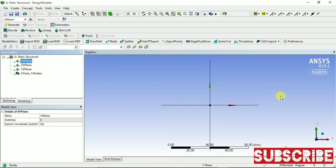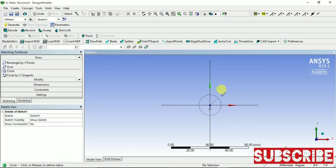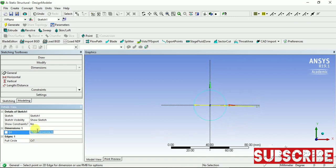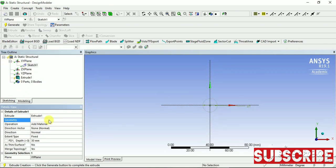I will show a very basic example to use this software. For example, say we take a cylindrical specimen. For that I will use a circle with a particular diameter, d1, say 15 mm. Okay, now go to modeling and extrude it. Add material, and put the length as 80 mm and generate it.